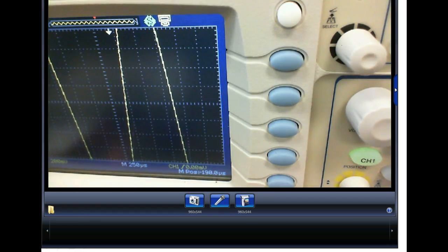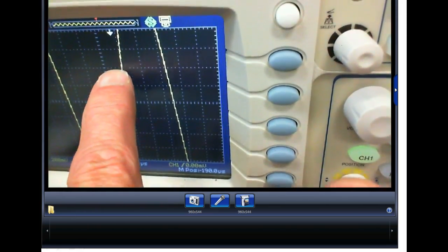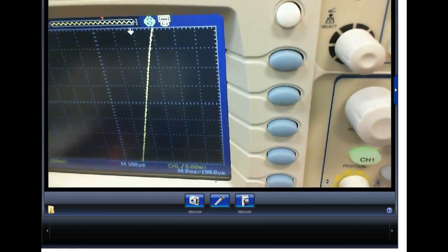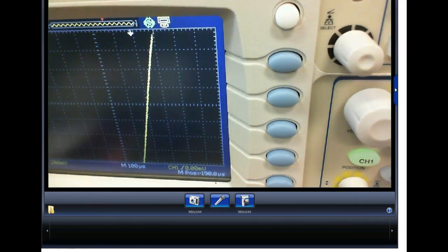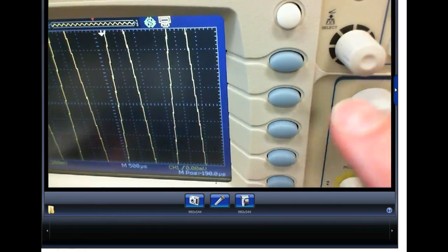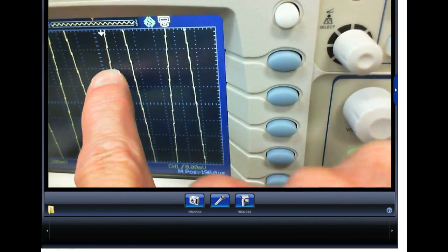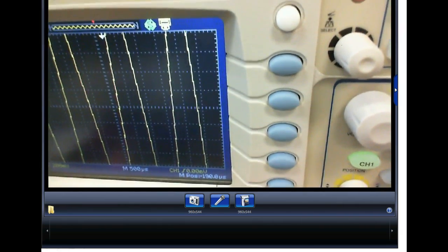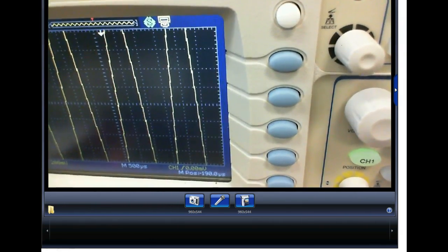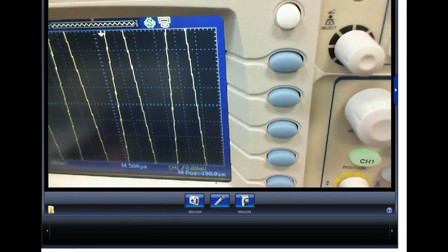We call it volts per step if you're into A to D conversion, or analog to digital conversion. We don't deal with infinity, so each step represents a certain binary number. Can y'all actually see the steps? Yeah, the little steps right there? It would probably show more if I increase the frequency, but I can't get to that. That's just something on a digital oscilloscope that you get used to, being able to see the steps, and you understand that they're not really there. This is a nice smooth signal, so it's not moving in these steps.